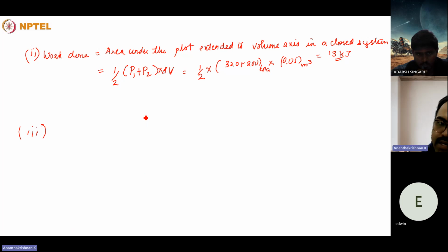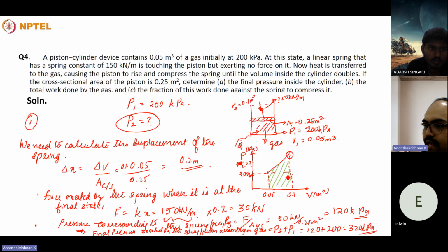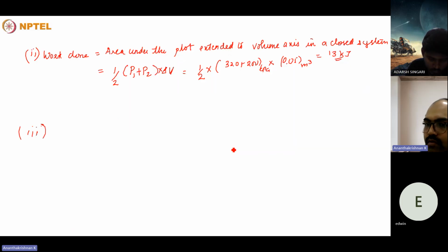But also it could be determined in a different manner. Basically, that is equal to the area of the triangle subtended between these two endpoints, so basically this top triangle area. That is also the same. In either way, you can calculate the work done against a spring to compress. It's a linear spring, basically. So we can write it accordingly.